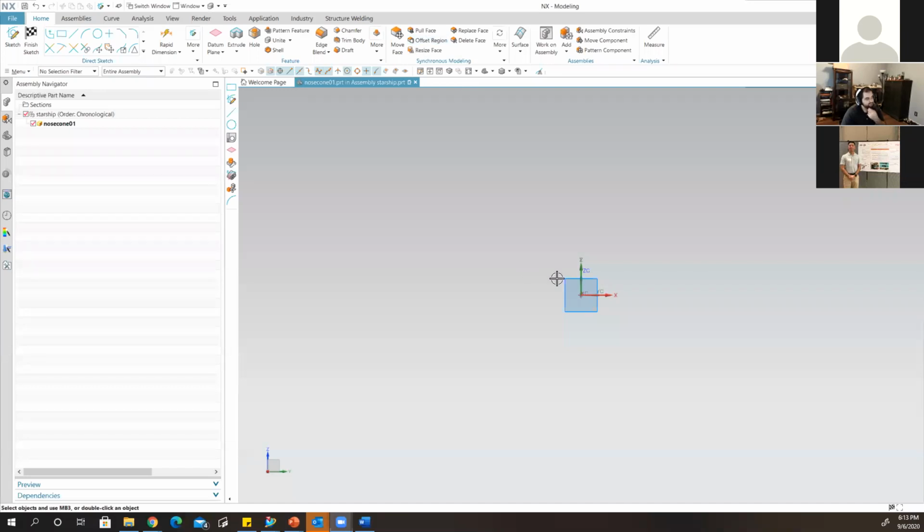So we're going to create the sketch. We already selected the YZ plane where we're going to create the sketch. Similar to other 3D CAD programs, you've got your basic forms like a rectangle, a line, an arc, or a circle. So what I'm going to do for this one, I'm just going to create a rectangle first.